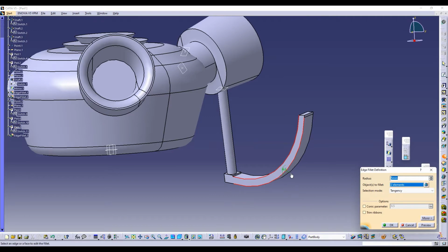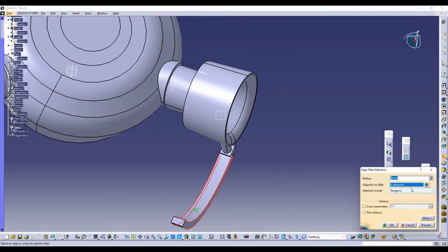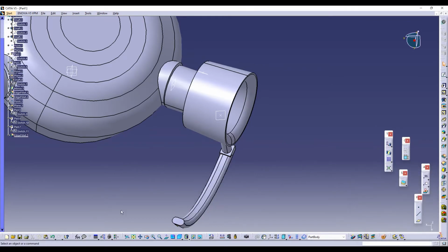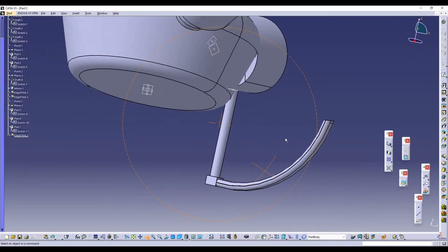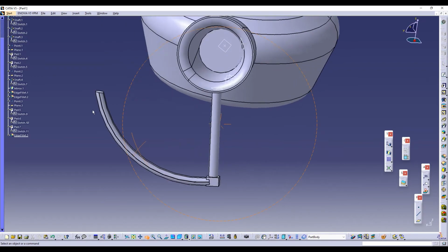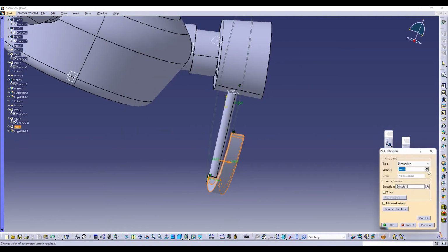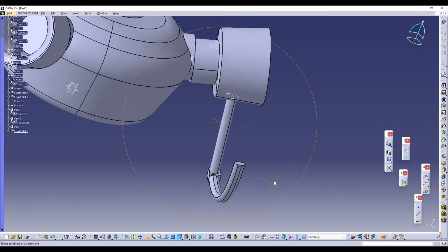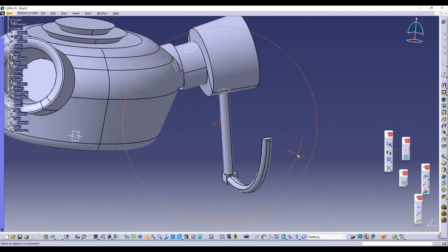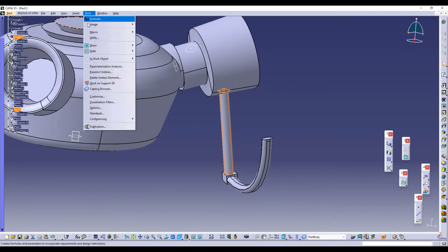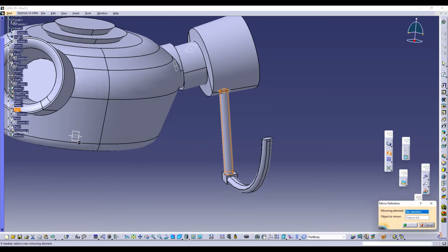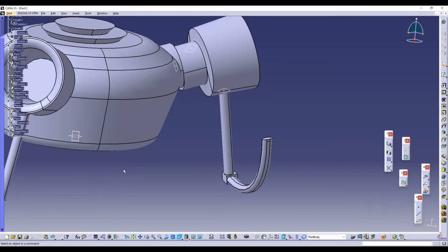We'll select all the sides. Okay, then it's done. 2 mm fillet. Okay, let's make it 6 and it's done. Mirror this structure. It's done.